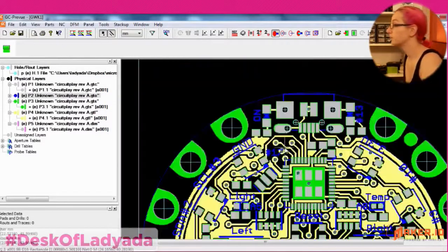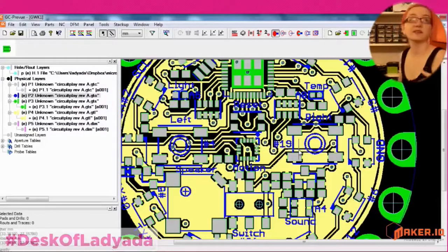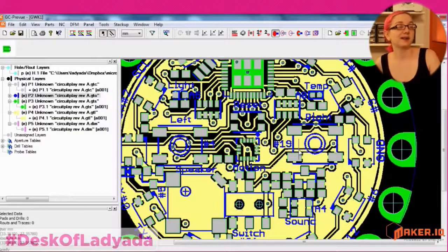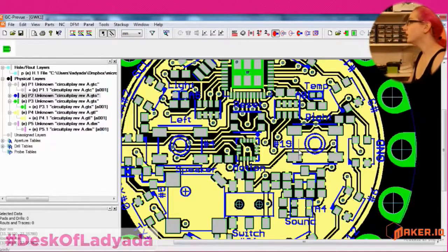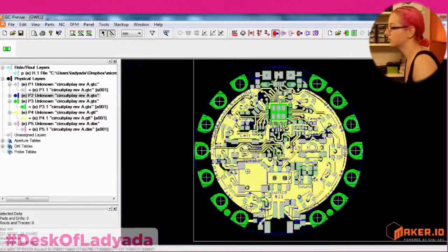And we have a machine that does this at Adafruit. So when you get the stencil manufactured, you can just give them this file. And again, if there's a mistake in it, you can edit it after the PCB is made, but before the stencils are ordered. But it's very icky, they're cutting sheets of metal with a giant laser. You want to make sure that this is right, and so you'll see the paste is just a little bit smaller than the pad. That's normal because you don't want it to bridge.